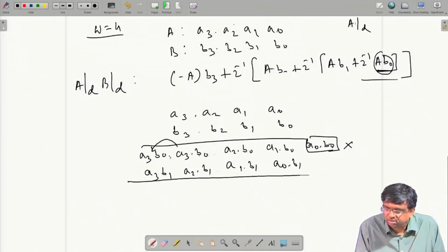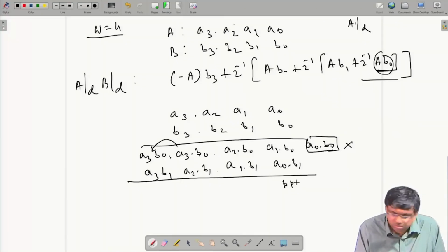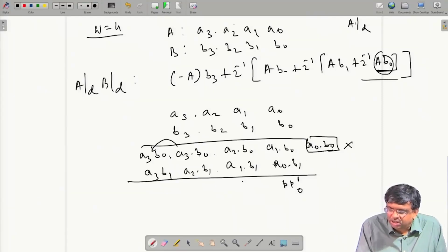You add. Whatever you get, some intermediate result, is called the partial product, PP. First stage, first PP, so there is a PP1, but it is the LSB. You add the two, incoming carry is 0 to the adder, and the result is here. That will generate a carry that will move to this side. So, this carry plus these two will be added, which gives the next bit of PP1, and again a carry will move to this side, this will be added, giving the second next bit of PP1, and they will get added.